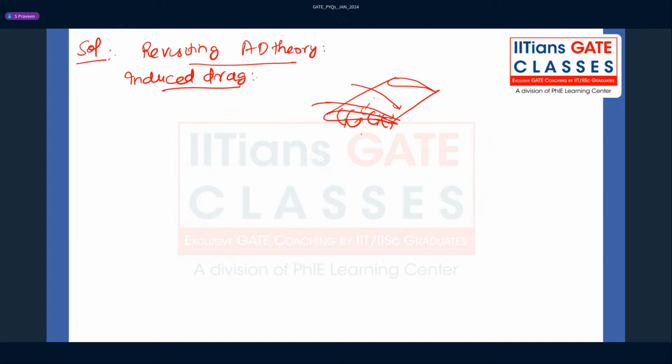This flow, if I look at it from this end, will bend the velocity this way. That is the downwash velocity. Since my free stream is approaching as V infinity, this is my effective downwash angle, epsilon or alpha, whatever you want to call it. To minimize this induced drag, they add winglets such that it cuts off the generation of vortices. That is the use.